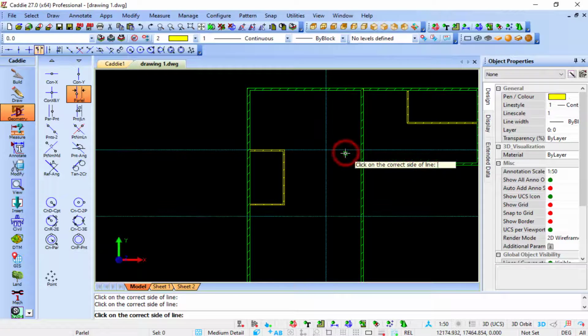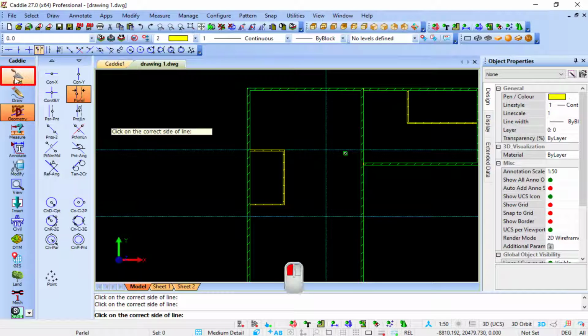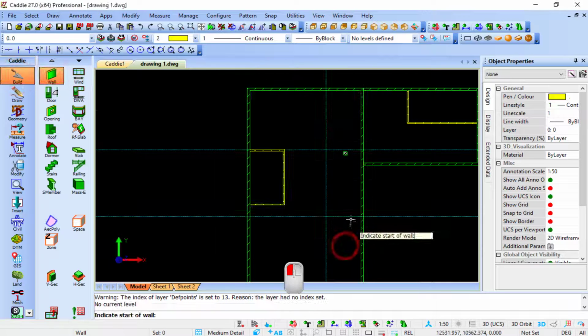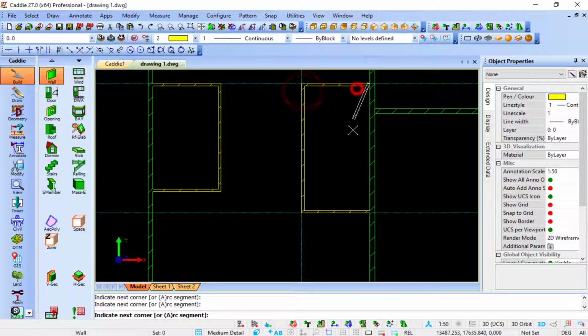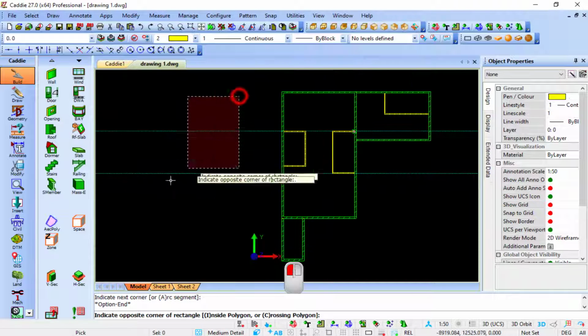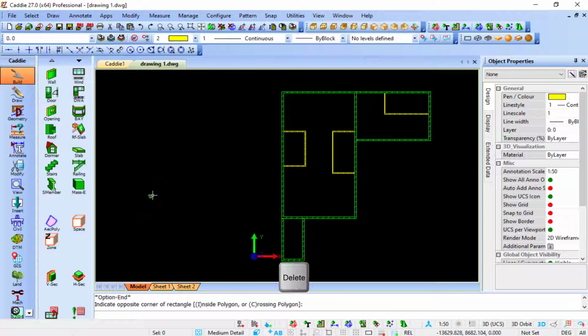parallel to my horizontal construction line. So 6 by 3, that will give me 18 squares. S for snap, I do get a signal, and I just go clockwise. E for end. You can select multiple objects and you can press delete as well.